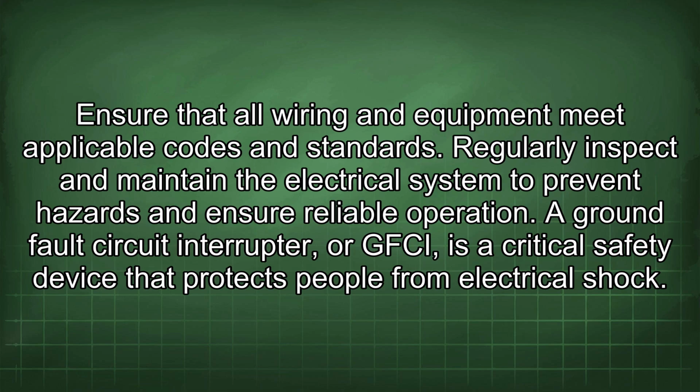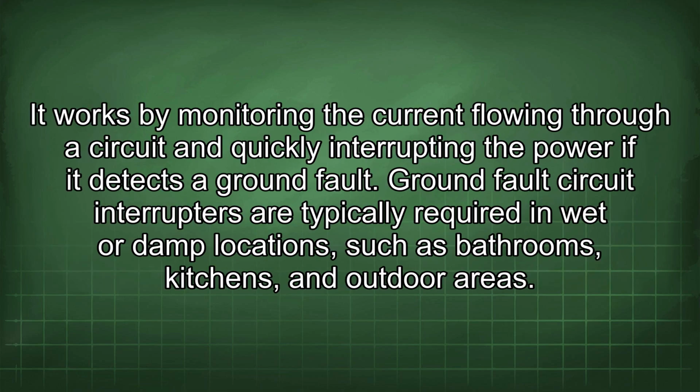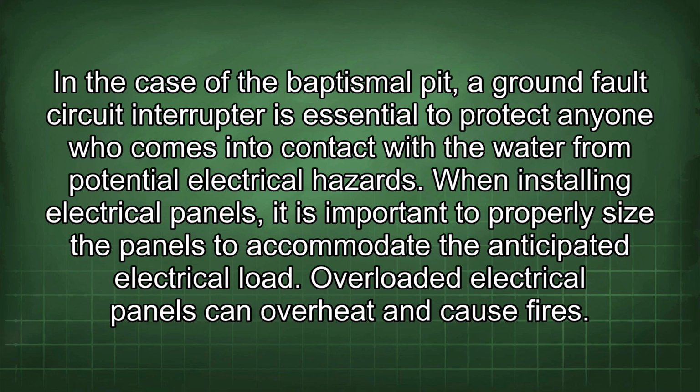A ground fault circuit interrupter, or GFCI, is a critical safety device that protects people from electrical shock. It works by monitoring the current flowing through a circuit and quickly interrupting the power if it detects a ground fault. Ground fault circuit interrupters are typically required in wet or damp locations such as bathrooms, kitchens, and outdoor areas. In the case of the baptismal pit, a ground fault circuit interrupter is essential to protect anyone who comes into contact with the water from potential electrical hazards.